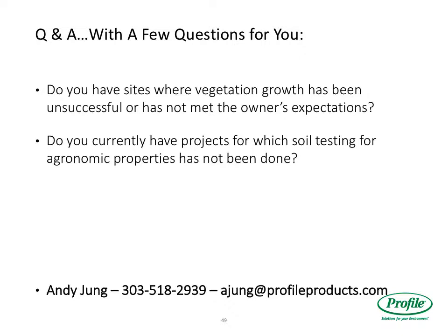Working for a company previously that sold geosynthetic liners, that was always a question: how is this thing going to last? You've got maybe 500 to 750 years, and then that liner is pretty much compromised. So it's a perpetual maintenance type situation. You're going to have to mow that site, essentially, which is why now I'm happy to be on the good side and promoting sustainable green solutions. So if you can design that ET cap right, which isn't always going to work. In some areas, if you've got 6 feet of snow and then a rain-on-snow event, it might overwhelm an ET cap, but in a lot of areas, an ET cap is going to perform very well. But with the synthetic cover, you're going to be looking at perpetual maintenance.